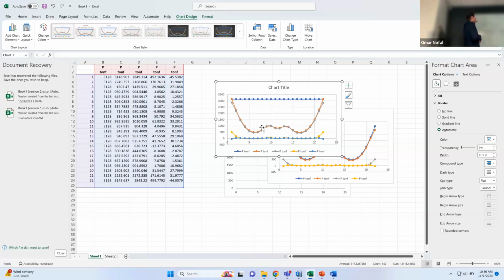If you want to do this, you will show me how you did this in detail. How you calculate I, like you make a special section in the report and say calculating the shear lag value, and then you show me these two equations and how you substitute with the moment, the inertia, and y, and you get the value of b, and you show me the values. You'll get the 5% points. All right, so that's it for now.